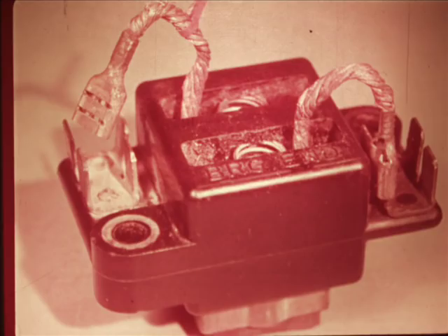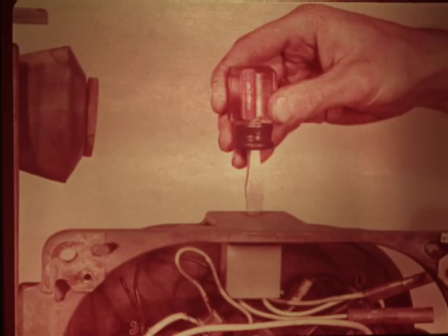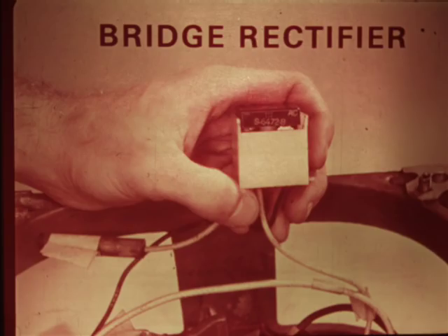When you install the brushes, make sure the side-stamped bearing end is toward the bell housing. Also, make sure the springs move freely after you tighten the block screws. You should next check the bridge rectifier. Remove this screw to separate the rectifier from the housing and disconnect the wiring connector. Before you remove it, observe how it's installed. The writing on the rectifier can be seen through the cutout on the box. If you reinstall it any other way, it won't work.